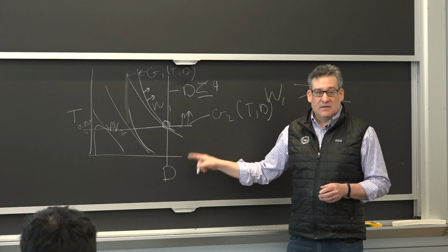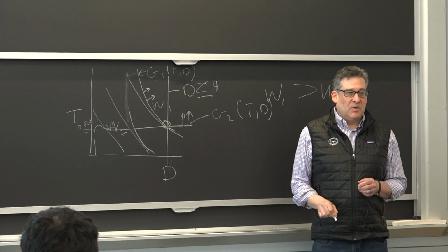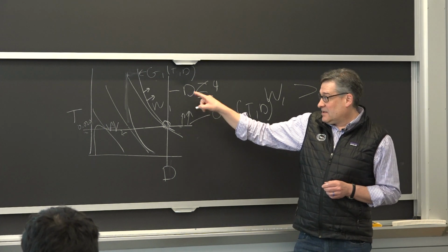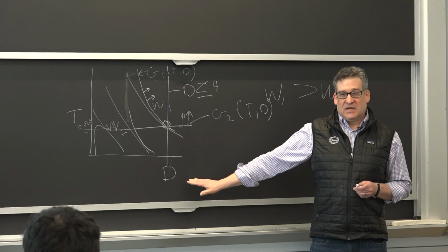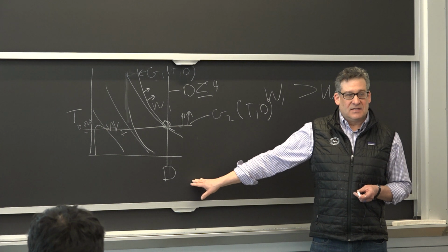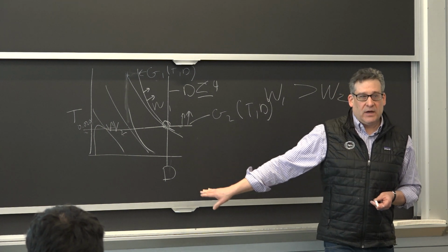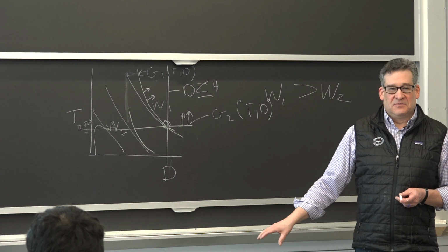You're dealing with a big D and a small t. This vertex right here, that's your point where you get the minimum weight solution, subject to these constraints, D and G1 and G2. Okay, does everyone understand this? Because this is the foundation for everything else we're going to talk about. This concept of exploring a multi-dimensional design space to find an optimum solution.